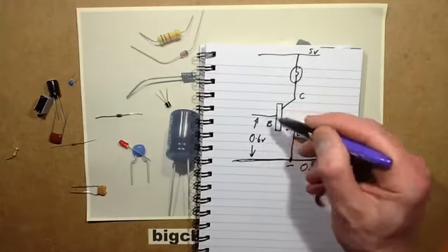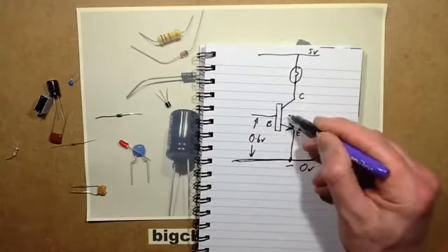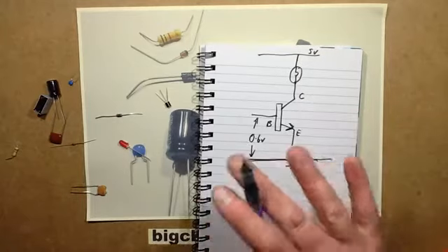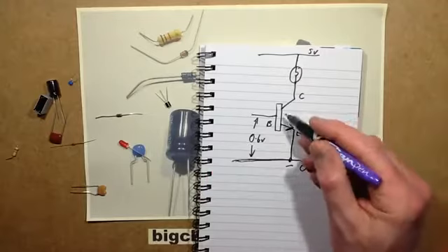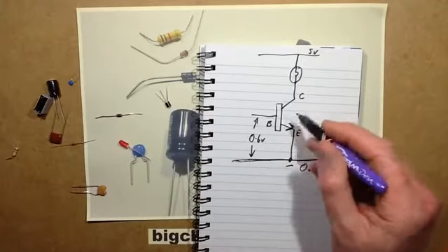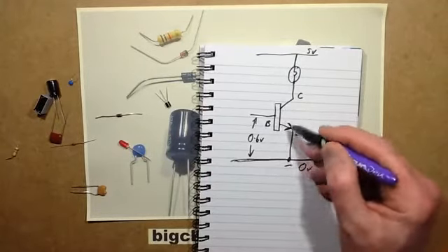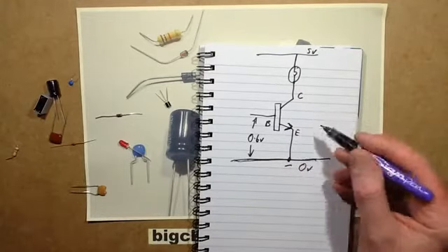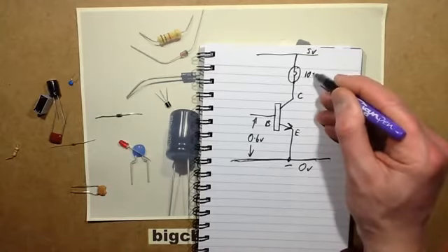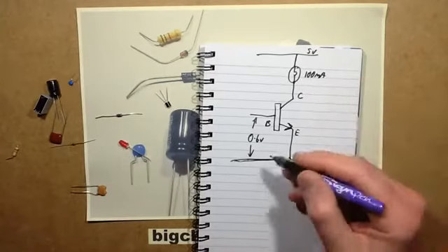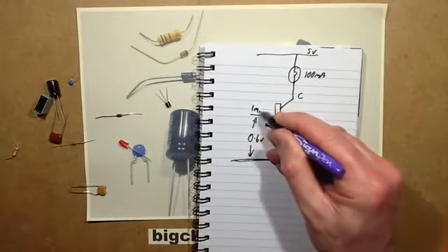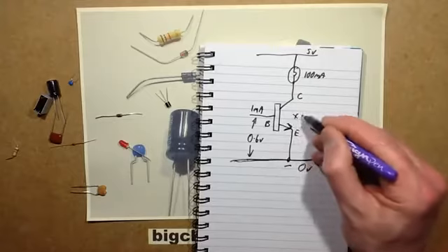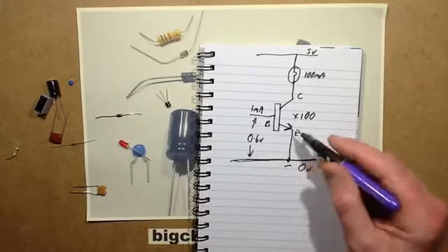a modest current, a transistor typically has a value called a gain. It's got a voltage rating, a gain rating, a power dissipation rating. There are lots of other ratings, but let's keep it simple. In most instances when you're using a transistor, it's going to be an NPN like this. So say you've got a gain of 100, and that lamp's going to pass 100 milliamps to light fully. Then you want to pass at least 1 milliamp into the base here, and that will then be multiplied by the gain of the transistor, and it will switch the lamp.